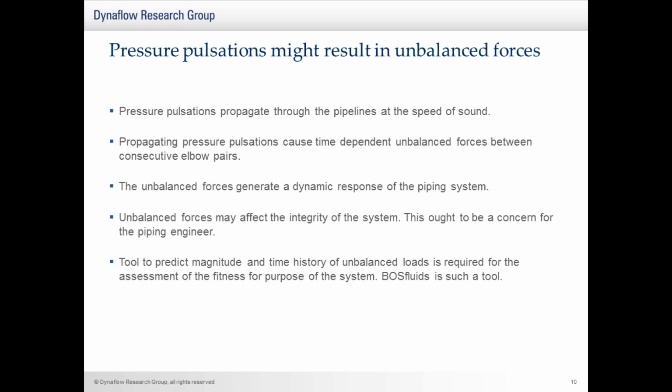Propagating pressure pulsations cause time-dependent unbalanced forces between the consecutive elbow pairs. The unbalanced forces generate a dynamic response of the piping system that may affect the integrity of the system, which should be of concern to the piping engineer.